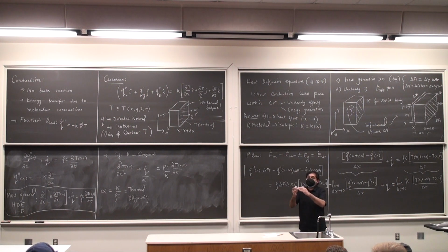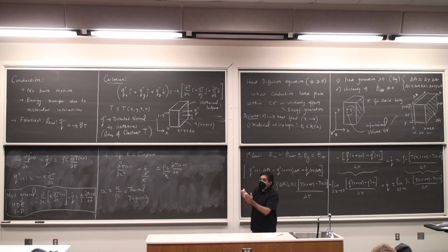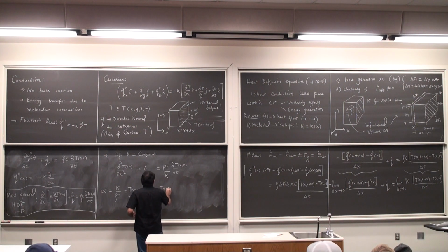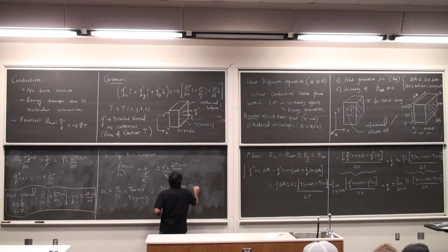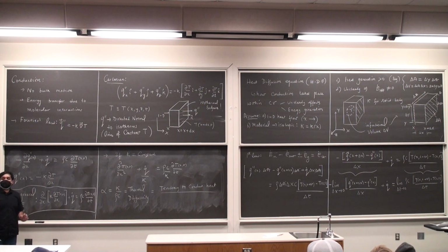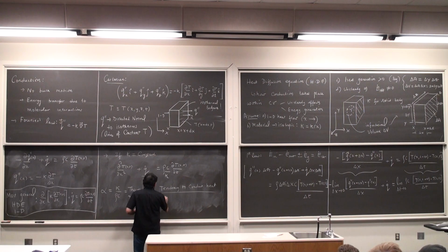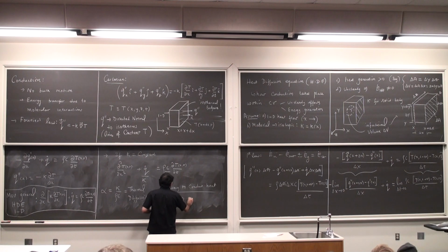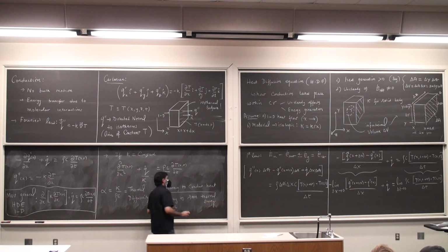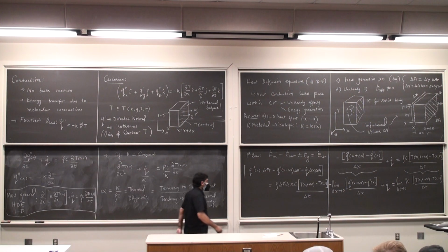It is a ratio of the tendency to conduct heat divided by the tendency to store energy. Rho times c is a function of how much energy is stored, density times specific heat. So this is tendency to conduct heat, which is what is represented by the thermal conductivity. Higher the thermal conductivity, greater the tendency to conduct heat. And rho times c is the tendency to store thermal energy. You'd have come across the term thermal capacitance when you did system dynamics at some point. You'll see those creatures coming into life again.